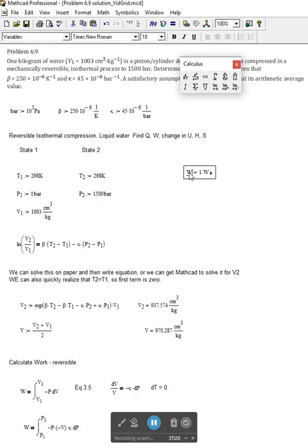So what that means is, if I were doing this in heat transfer, where joules per second is a watt, or for an electrical engineering physics problem, I would not want to use W as a variable. If I have a heat transfer problem and I am calculating work, it's going to really screw me up if I use W as my variable for work, because MathCAD will always think that is a watt.